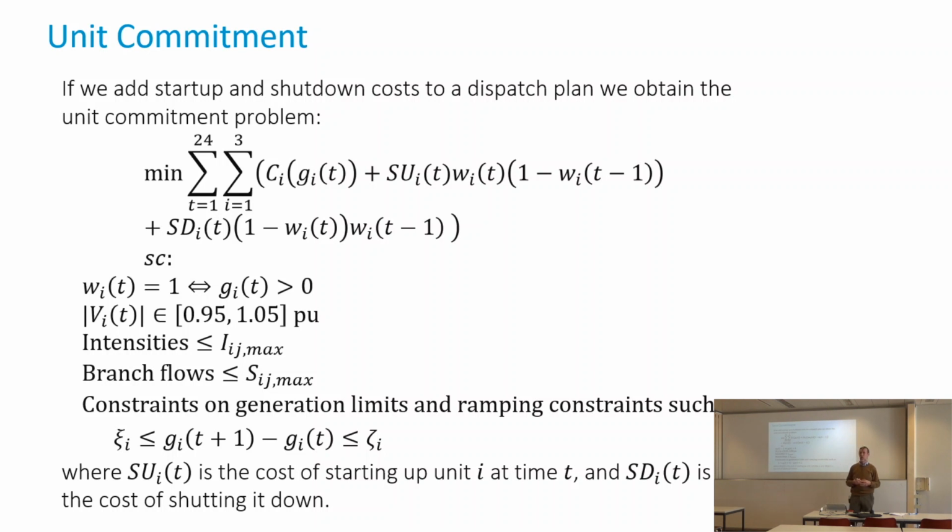Every country or every area in a country has one transmission network that's under the control of one transmission network operator. And then you have zillions of distribution networks that are under the control of municipalities or other operators. In distribution networks, the resistance components of the lines are often important, so we may not be able to use the DC approximation in distribution networks.